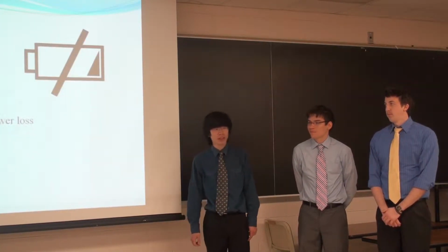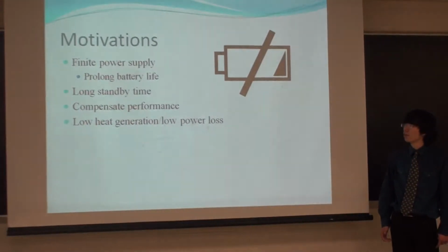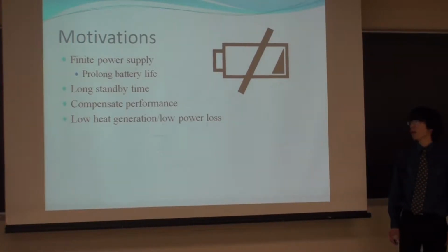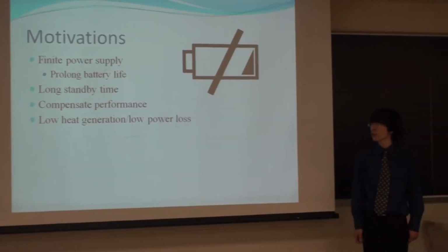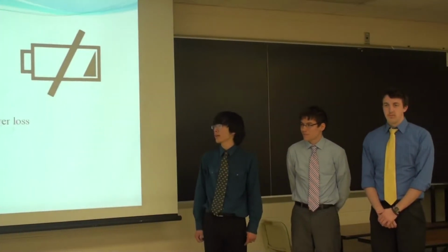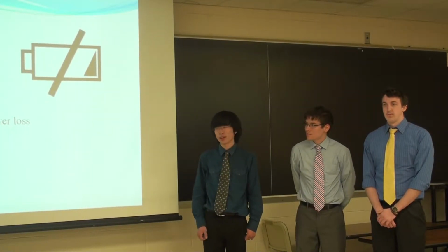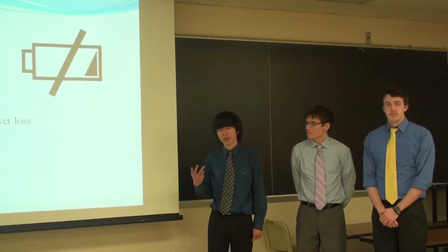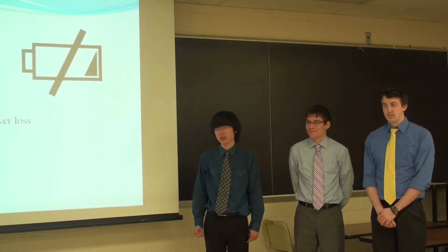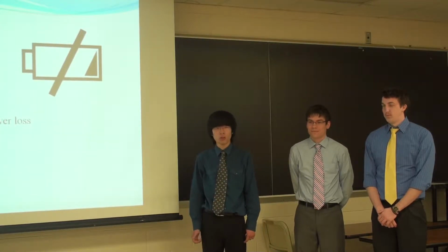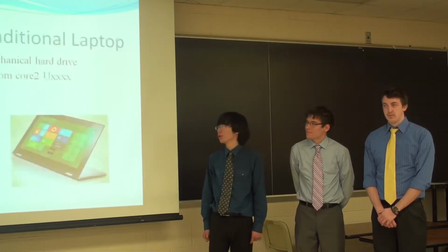The motivation for designing a low power embedded system is, first of all, we have a finite amount of power supply, which is powered by a battery or solar panel or something. Also, it needs a really long standby time, and sometimes you can compromise on performance, which means you can underclock or just run in a low battery consumption mode. Also, with low power consumption, we can generate low heat, and there will be low power loss too.